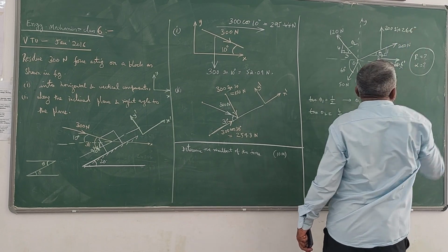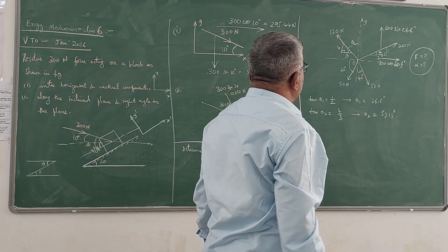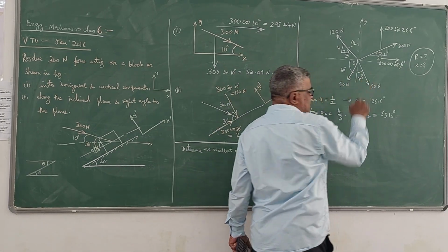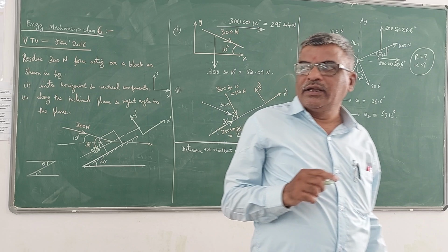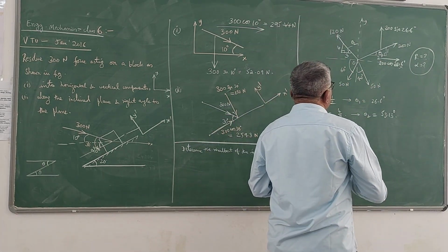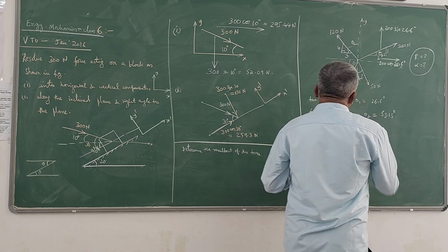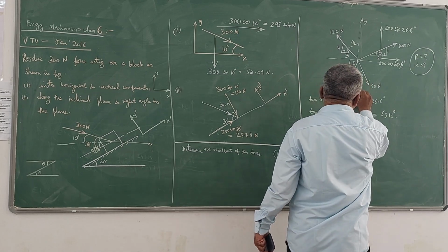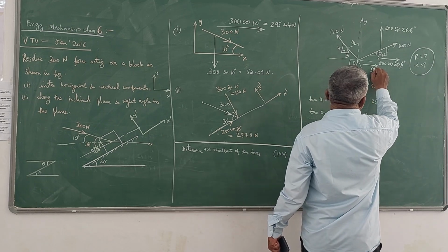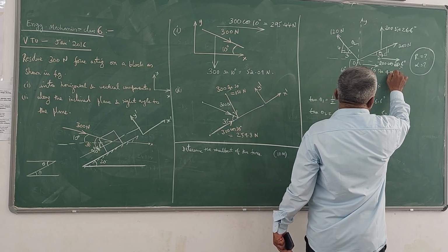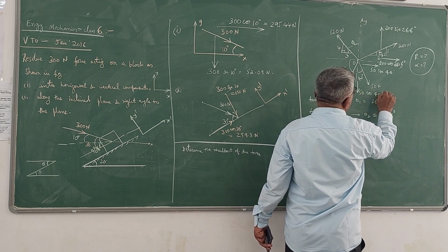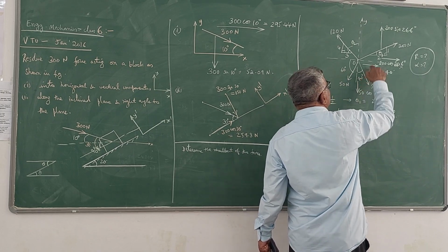So find out the angle from the slope. Here, in terms of angle only he has given. Of course, the angle is given with respect to the vertical. When they give the angle with respect to the vertical, this component becomes cos. This component, because this is the adjacent angle, becomes sine. So that means 50 sin 40. This is 50 cos 40. Otherwise, you have to convert this 40 with respect to the x-axis.